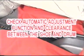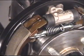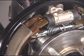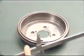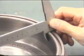Next, check the automatic adjustment function and the clearance between the shoe and drum. Confirm that the adjustment bolt rotates as the parking lever is being pulled. Check the clearance between the shoe and drum. Release the parking brake.